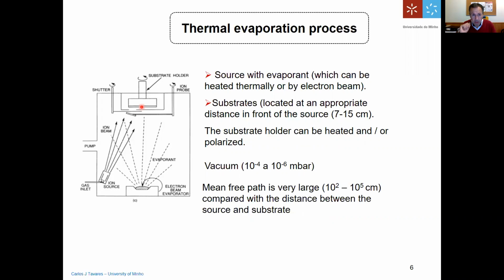In comparison to sputtering, for example, as I will show you in the next chapter, for specific films, especially when you deposit materials like titanium nitride on cutting tools, the adhesion is very strong, and you have a film which is mechanically very tough, with high hardness and a high Young's modulus, or very high modulus of elasticity, okay?